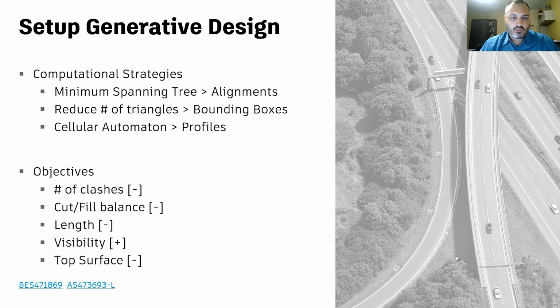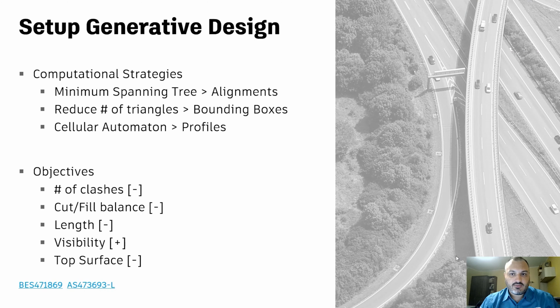When it comes to road design, typical objectives could be minimizing the number of clashes, minimizing the cut and fill balance or the cut and fill total amount, minimizing the total length of the road, maximizing the visibility, or minimizing the finish ground, so the extension of the top surface. In the bottom left corner, you will see references to other Autodesk University classes where you can get more information around how to set up a generative design study.